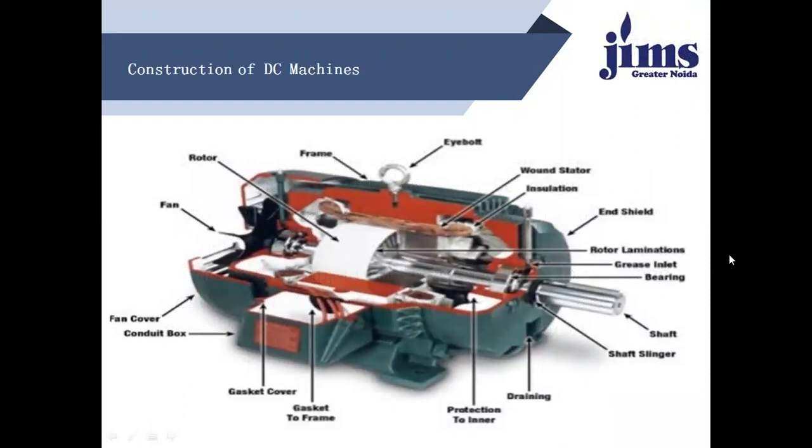This will be the construction of the DC machines. Over here you can see an outer cage, which is called the frame of the machine. There is an eye bolt. The eye bolt is used just to pick up the motor from one place to another. There is a frame which is associated with many parts of the machine. Over here we have a gasket cover, a gasket to the frame. This part is the cover to make the electrical connection of the machine, either a motor or a generator.